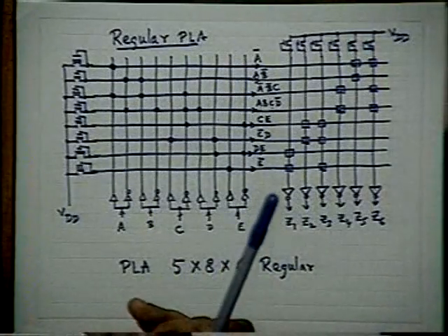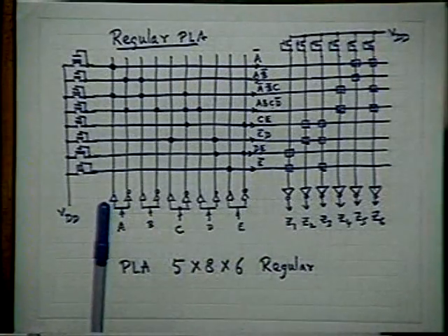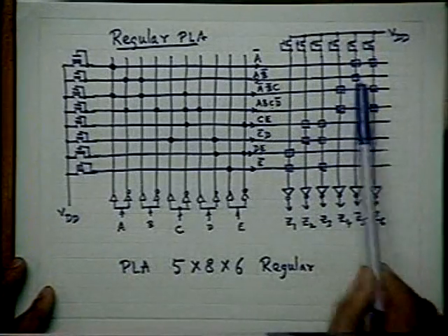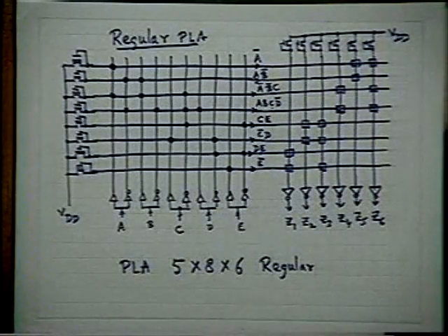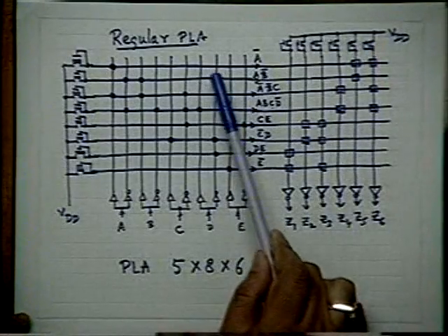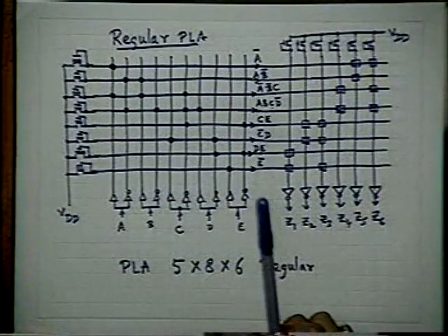They are all available, but I am not utilizing them. Similarly, in the columns of the OR plane, this picture is very similar. So naturally, these transistors are occupying unnecessary areas. This is not leading to a high packing density. Design is simple, but there are 2 bad aspects of it. One is that packing density is less, that means complexity is less. And secondly, I have to use longer wire routes.